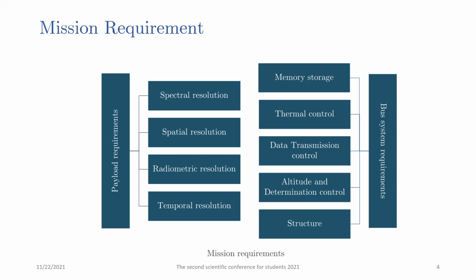For the attitude design and control system, the possible accuracy can range between 0.05 to 0.2 degrees during nadir pointing, which is 5 km to 22 km on the surface. And finally, the payload size weight ranges between 17 and 50% of the spacecraft wet weight.